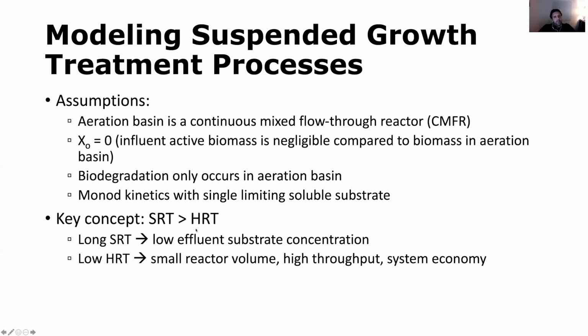The key concept for suspended growth treatment processes for biological systems is that SRT is greater than HRT, and that's due to the sludge recycling that takes place. SRT being the solids retention time and HRT being the hydraulic retention time.